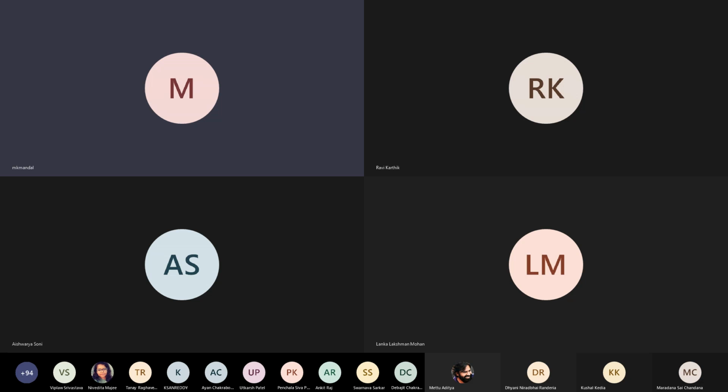So the best way from this field matching or mode matching point of view, I have to align the ground of the microstrip line here and the top plane here. Then we have the electric field in the same direction. So for the microstrip line, let me represent it by a black line, and for the rectangular waveguide, TE10.